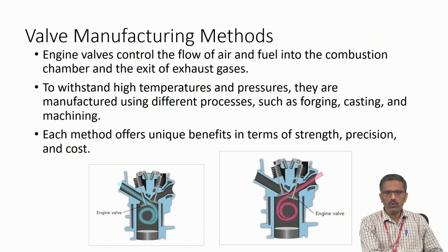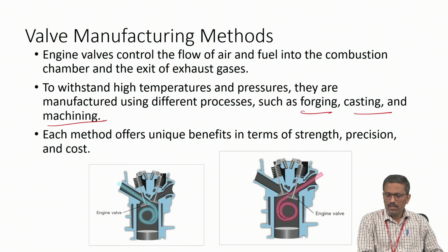These valves we use in the engine to control the flow of air, that is inlet, and fuel into the combustion chamber, and the exit of exhaust gases through the exhaust valve, to withstand high temperatures and pressures. They are manufactured using different methods such as forging, casting, and machining. Each method offers unique benefits in terms of strength, precision, and cost.